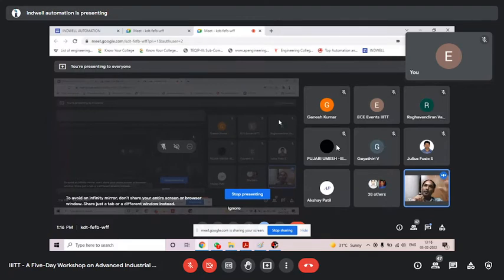So simulation means what? With HMI software, you can simulate the machine and operate it from the HMI software, even though hardware is not connected. You just want to check your HMI software design, whether it is working or not. So in online simulation you can check that. Another thing, offline simulation is also available. So both are available. You can check that further.